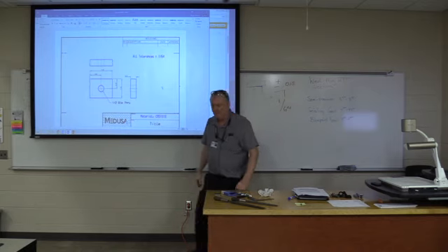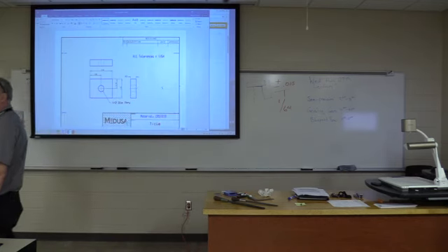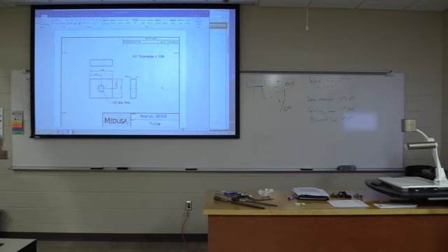That's your sort of working tolerance with semi-precision. Now filing, I spec'd out in the assignment 5 thousandths. That's pretty easy to do with this material in a file. You should be able to see that it's very nice and flat. But that's all this assignment is, a layout.